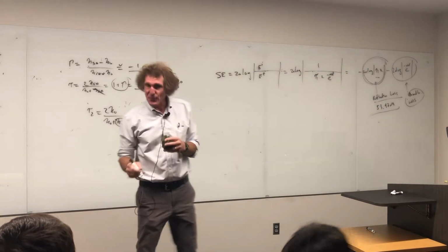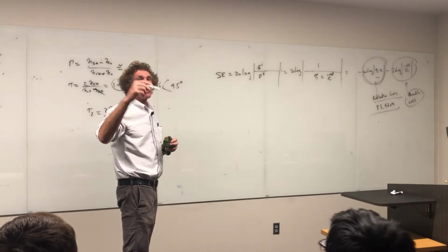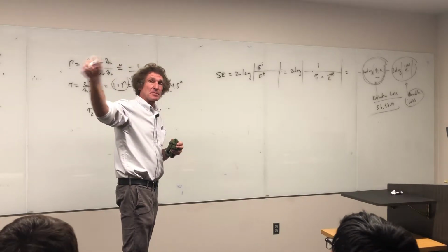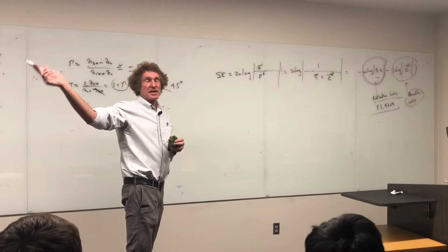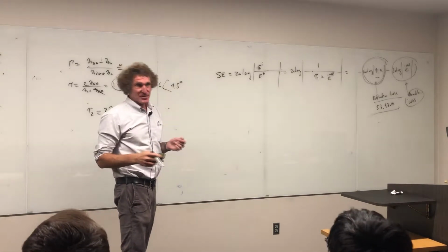Well, yes, that would do. For this problem, yes, you're right. Technically, you would say gamma is the square root of j omega mu naught times mu relative times sigma plus j omega epsilon, right? You can get rid of the j omega epsilon, and it does come out that alpha is about 1 over the skin depth.